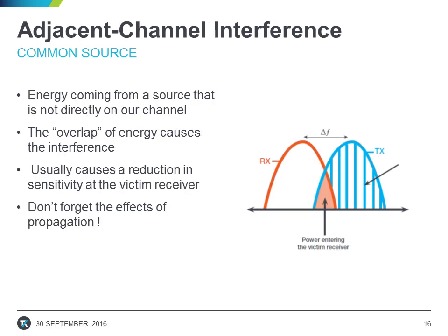Adjacent channel interference is somewhat more complex. Essentially, adjacent channel interference is any energy that's coming from off channel. It's the overlap area or the contribution from the adjacent source that causes problems in the victim receiver. Essentially, what we normally see is some form of desensitization or blocking of the victim receiver. This manifests itself in a smaller coverage area.